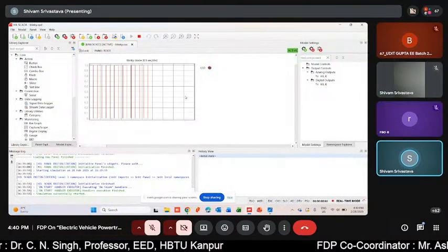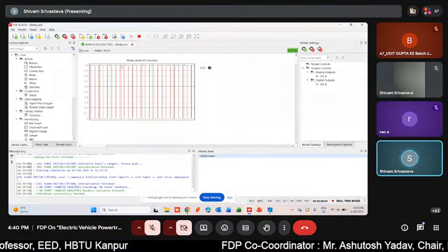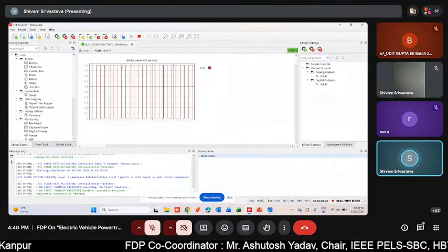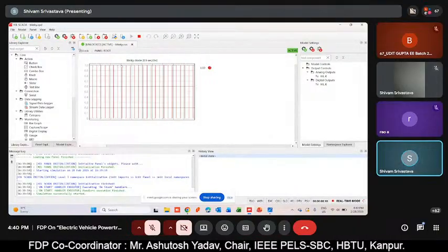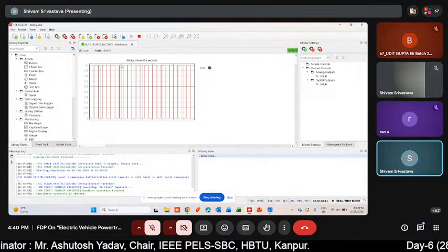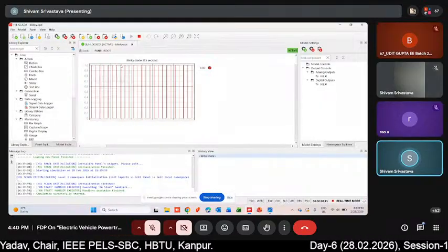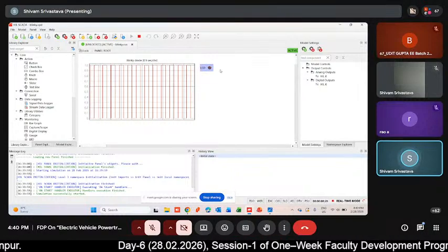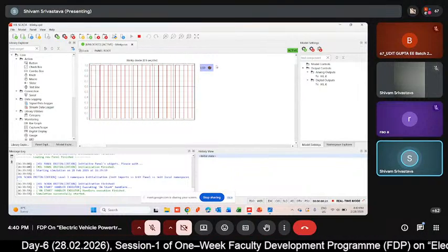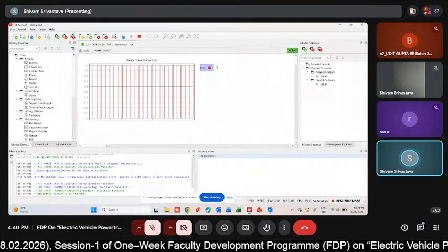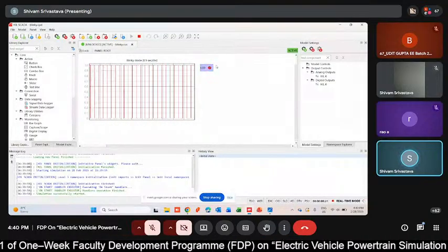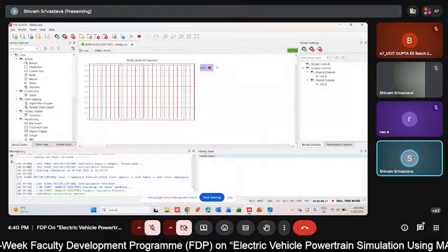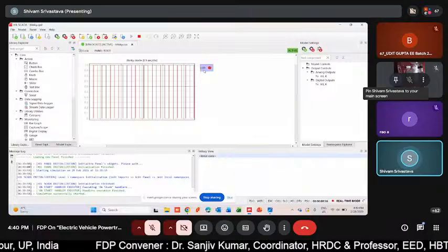It will give you the idea that the blinking of the LED is continuously happening as per these pulses increasing, decreasing or just appearing. But the LED tab you can observe on the screen right now is not appropriate with the waveform we are getting. This is because this LED is running on the CPU of the HIL device, while the waveform that we are getting is according to the FPGA controller card we have.